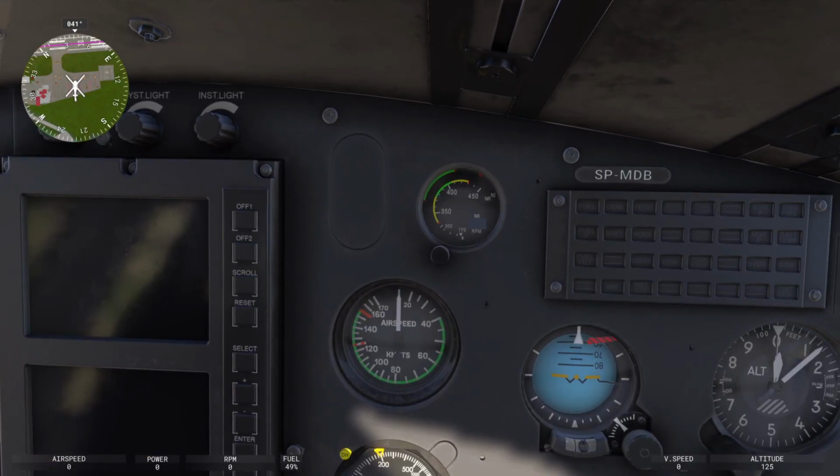What if they're not running at 100% RPM? I can show you that later. Essentially, what will happen is you will crash and burn. Okay, so as soon as it drops below around 93 to 94% NR, you're going to have a reduction in lift. You're going to have issues. If you don't sort it quite quickly and you drop below 90 to 92, and we'll talk about why those figures are important shortly, you're going to fall out the sky. Okay, the aircraft can no longer sustain flight.